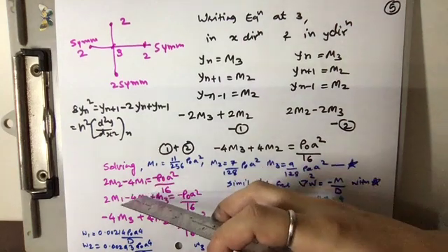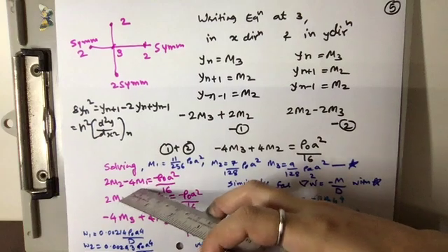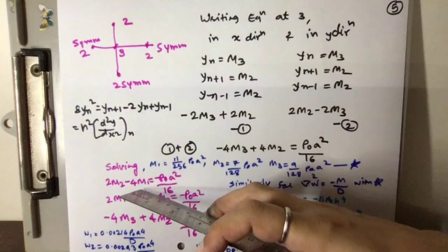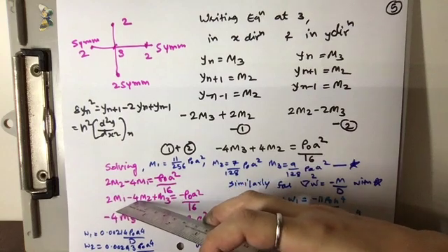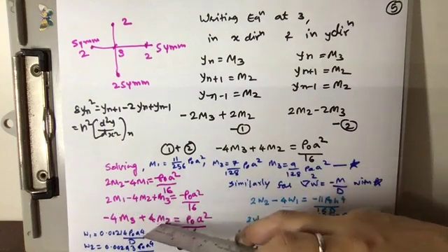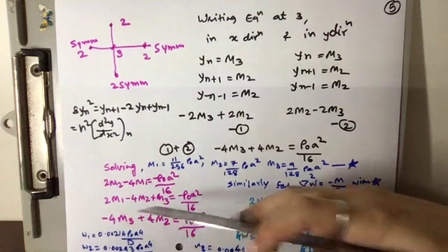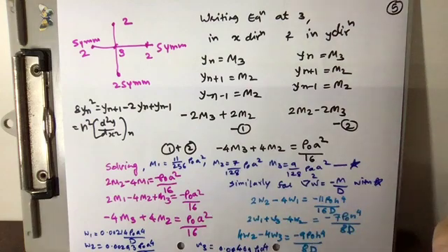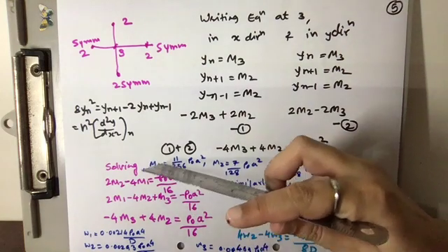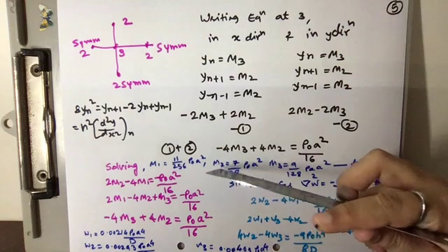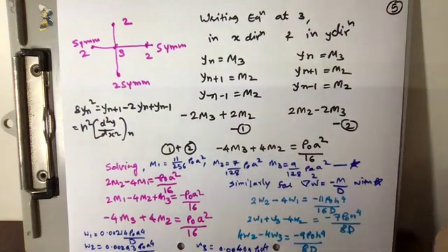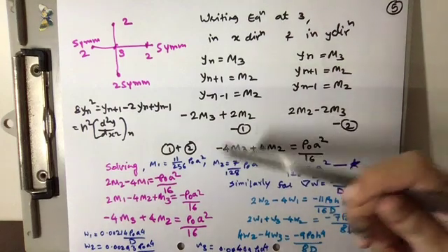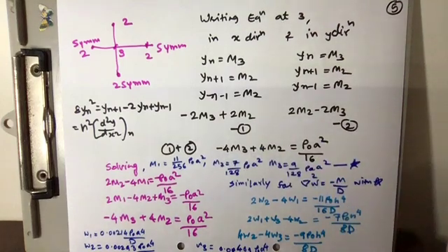So you can see here one of the equations not having m3, and you can solve this equation by hand by substituting m1 into this equation, and you get all your equation in terms of m2 and m3, and these two equations later on you can solve. Or you can adapt any other method for solving the simultaneous equation. When you solve, you are going to get this m1, m2, m3, your moment values at that particular points, and also at the symmetry points where these values are matching and the same.